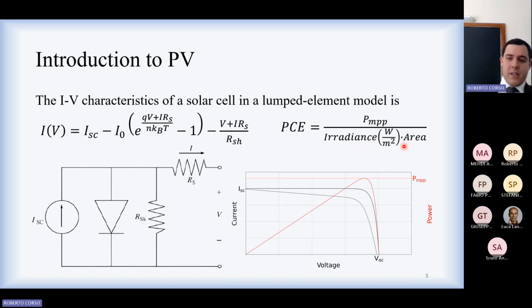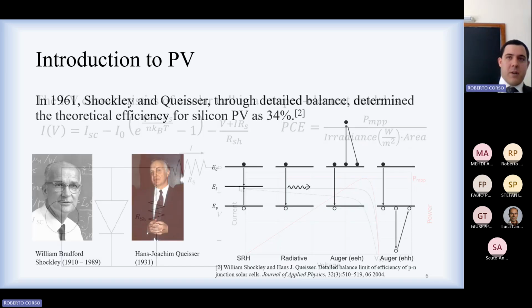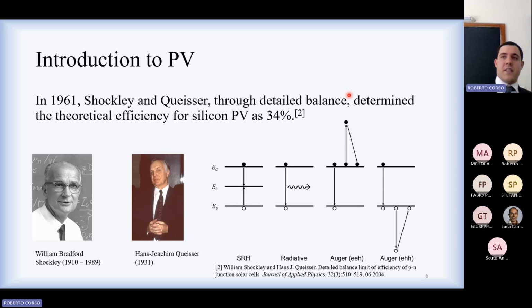The most important work in this field is the one published by Shockley and Queisser in 1961. In this work, the detailed balance principle was used. That is, they identified the incoming energy towards the system and a balance between generation and recombination processes, between each phenomenon and its opposite, in order to obtain the ideal current voltage characteristics of a solar cell.